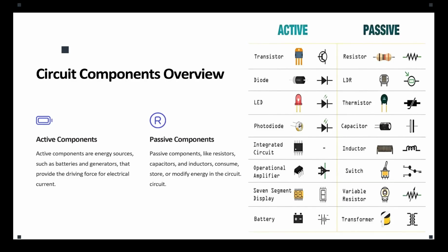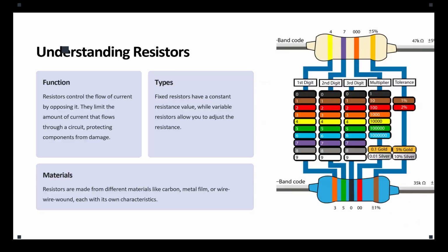We said we have several types of components. I'm not going to go deep into that, just listing that. We have active and passive components. The passive components are resistors, different types of resistors, capacitors, inductors, switches. The components that do not actively change the IV characteristic, current voltage characteristics. So they just passively follow the circuit rules. In active components, we have different kinds of behavior. We are going to see that later on during the course.